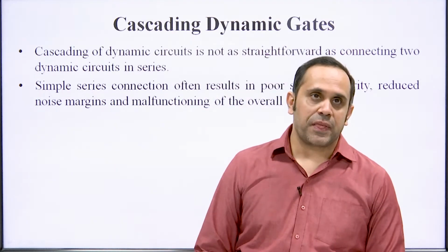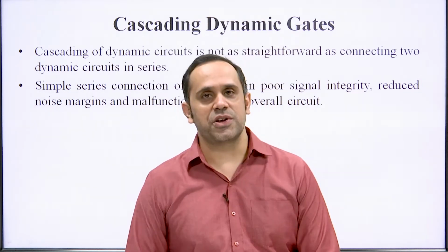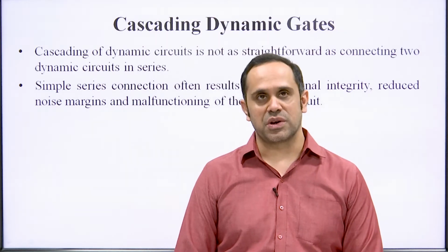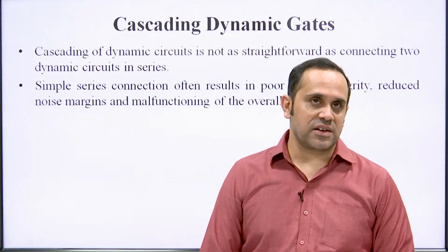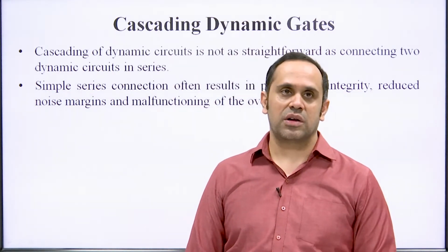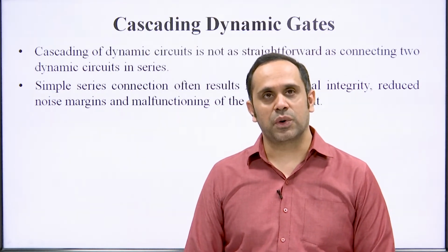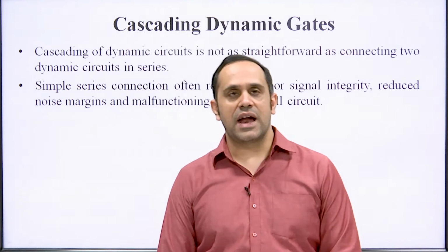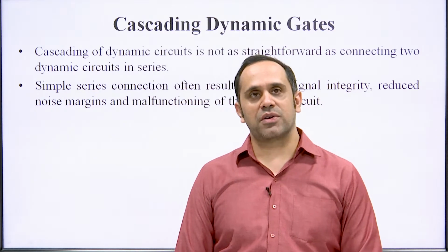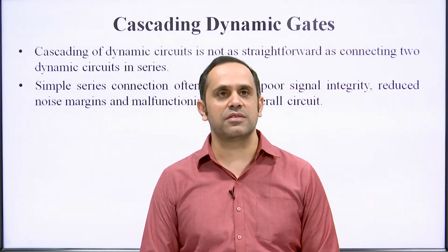Just to summarize, a dynamic CMOS circuit has two distinct stages of operation, number 1 being pre-charge and number 2 being evaluation. As compared to any static CMOS circuit, a dynamic CMOS circuit involves the use of a clock. When the clock goes low or logic 0, the pre-charge state comes into action and the output capacitor or load capacitor charges to the power supply VDD. So, your output goes to logic 1 during pre-charging when the clock is low.